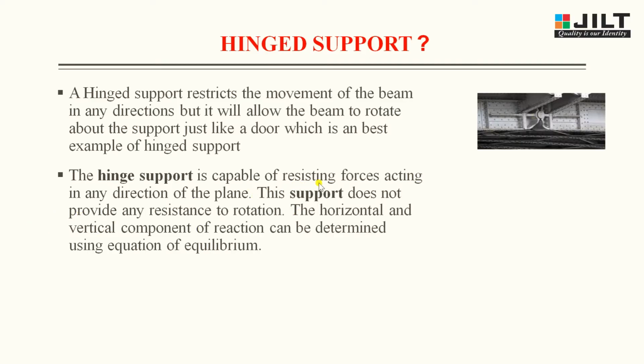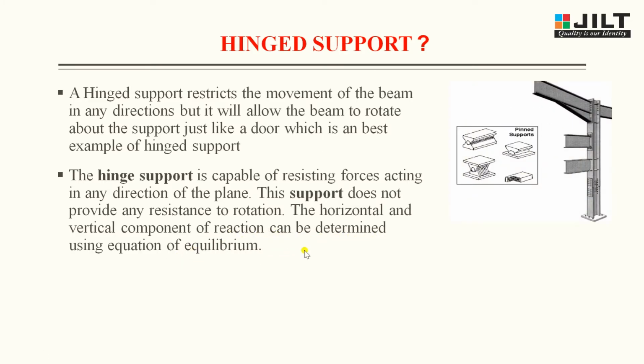The hinged support is also capable of resisting forces acting in any direction of the plane. This support does not provide any resistance to rotation. The horizontal and vertical components of reaction can be determined using the equations of equilibrium. This image also shows the hinge or pinned support.